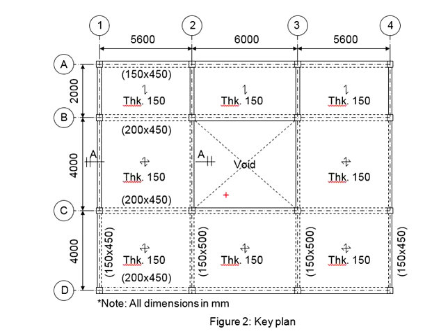That means the main reinforcement will be in these directions, which is the shorter span. As for the secondary reinforcement, it will be on these directions, in the transverse directions. Because of this, the main reinforcement will be the bottom layer of rebar, followed by the secondary reinforcement.